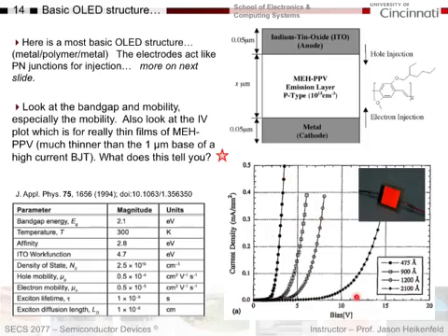And that's a challenge because if you make a layer that's only 200 nanometers thick and you have to apply 10 volts to get the current started, if you have the tiniest speck of dust, that will cause a short between your electrodes and cause this device to blow up in a puff of smoke. And so that's one of the challenges they've had that has slowed adoption of OLED displays.